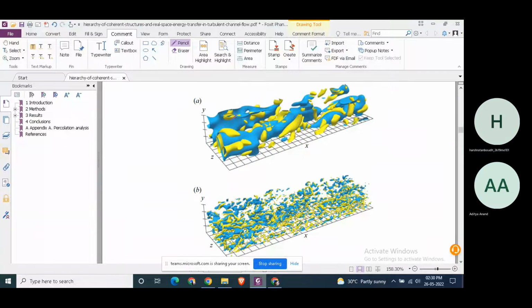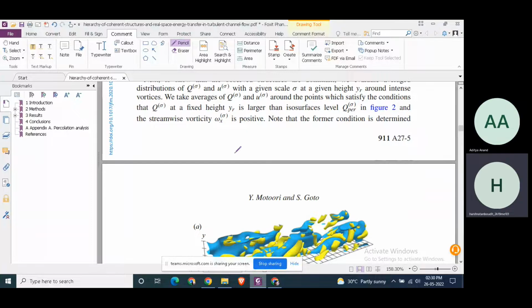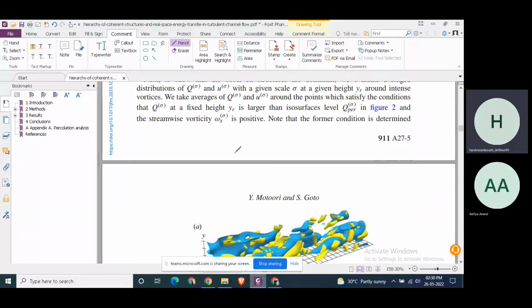Harsh, can you explain that decomposition again? Like the fluctuating velocity has two parts, decomposed into this, right? At any instant, there is a velocity. Like we have a signal, right? The velocity keeps changing. So what we can do is take a mean of the velocity, and the mean part goes like this. At every point, the velocity can be written as the velocity due to the mean and the velocity due to the fluctuating part.